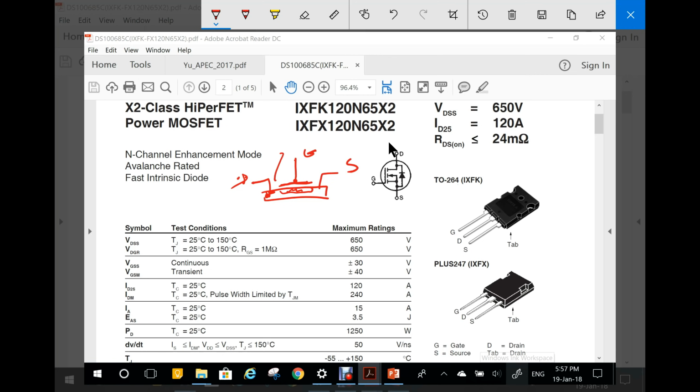This is insulation. Now, if you exceed these values, there will be a short in this insulation, and that's the end of the transistor. Now, this could be a very short pulse, and in some cases during transient phenomena and maybe some radiation from other units, you may have a high voltage imposed here.